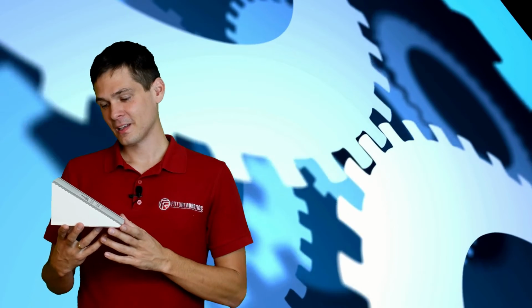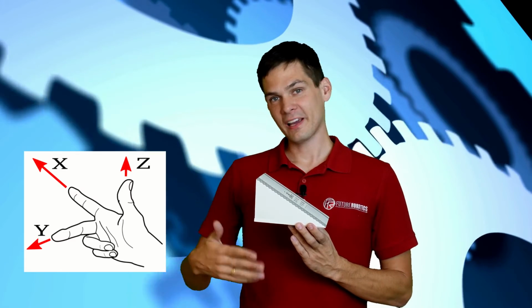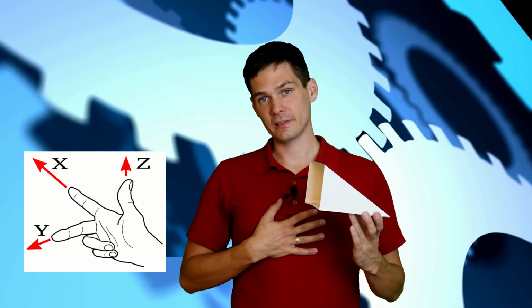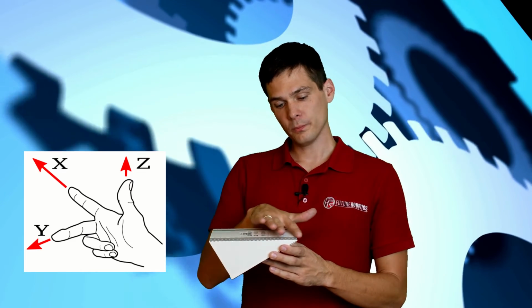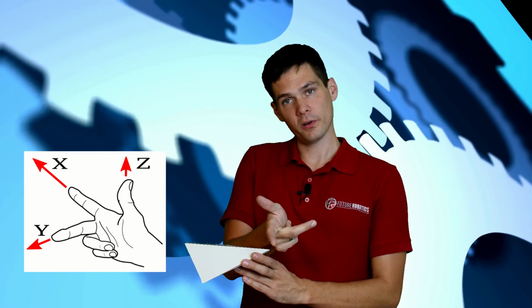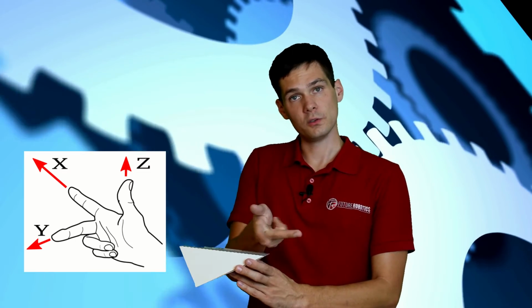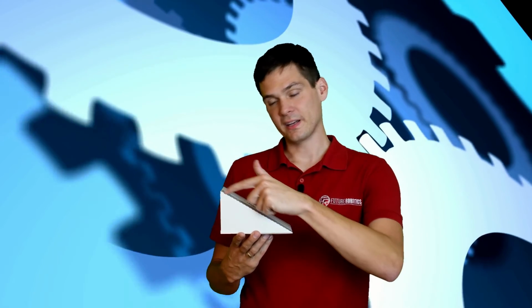Okay, the right hand rule, I hope you remember it, guys. So the right hand rule will still apply like always. So as I said, I'm the robot base. That's your right hand rule for the robot, for the world coordinate system, and for the base 0, as I said. Now what you're going to do, wherever you will pick your 0, let's say in here, you're going to move your right hand rule, the origin, to this point. And you can define it which way you want to go. Also very handy, because let's say for one of you, you want this to be your X direction. For other guys, you want this to be your Y direction, and somebody else might say, no, I want this to be my Z direction.